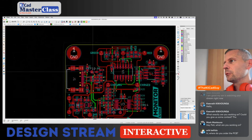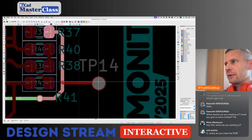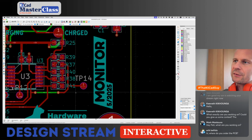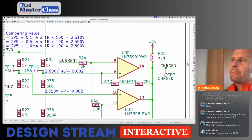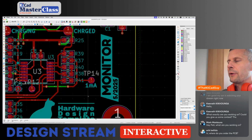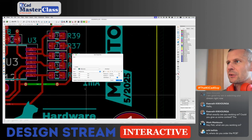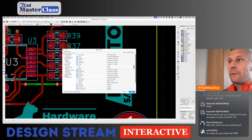So this is one of the edit labels, and I will move it slightly far from the newly placed resistor to be able to place the designator here. Here is the 1 milliamp label, and you can see that I placed the new label and it was quite thick. This is why, because I previously changed the default values.